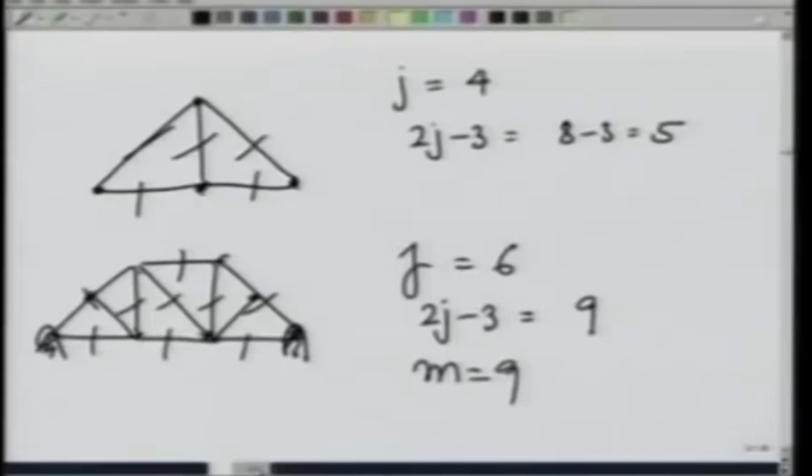In the previous lecture, you notice that both the ends are put on a fixed point. Actually, this makes the system indeterminate because the number of external forces is now 4. We could make it determinate by putting the right hand side of the system on a wheel or on a roller. Let us take one example of this.